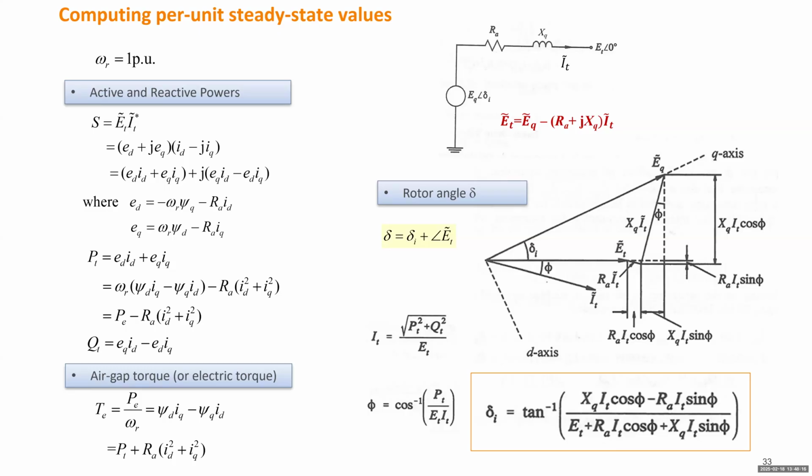So in the homework, you're going to solve for some conditions with different power factors. Keep that in mind: make sure to draw the phasor diagram and decide which triangle you're going to utilize to calculate the tangent of delta, and then you can check the formula to make sure all the signs are correct. Any questions?